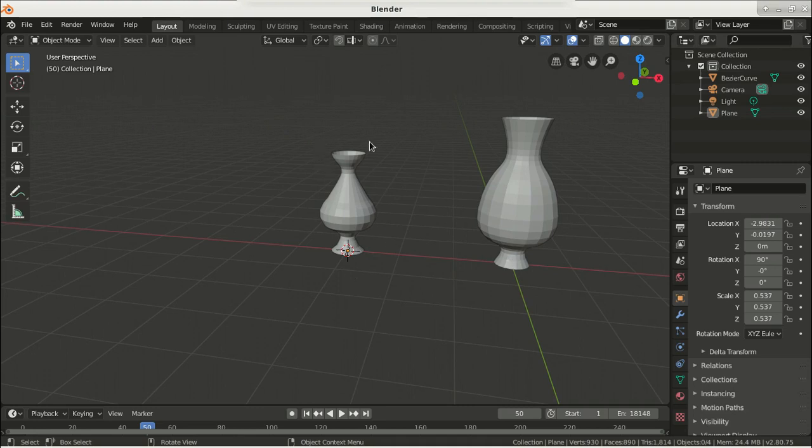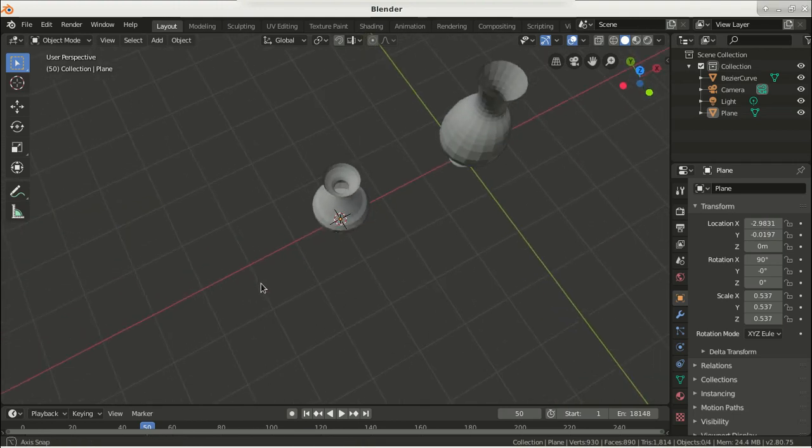In the next shape, we have created the outline by extruding our vertices using the control left click command. Once the outline is complete, make sure that the 3D cursor is at the point around which the spin tool has to spin those vertices, and the rest of the steps are the same. So this is all for today's lecture.